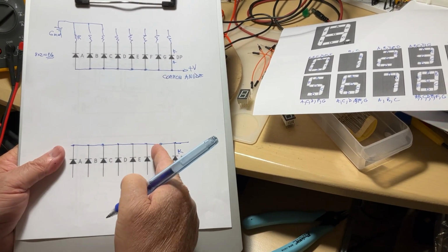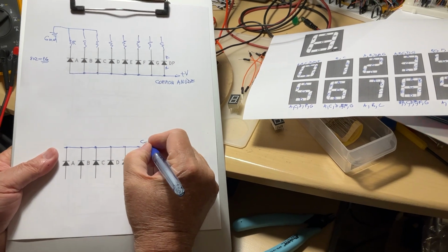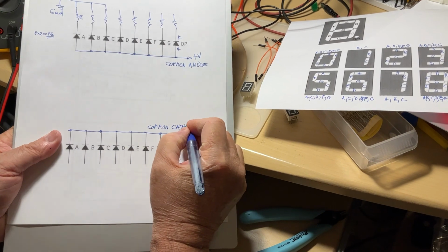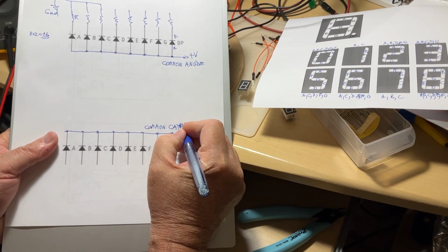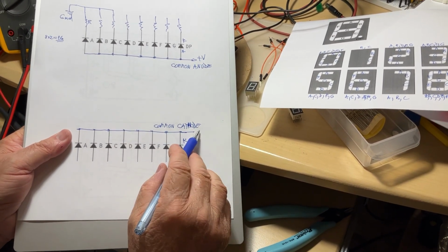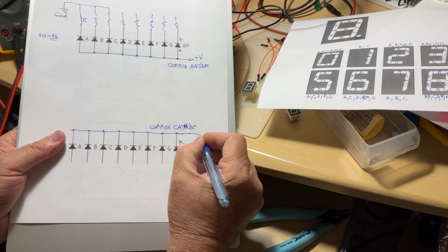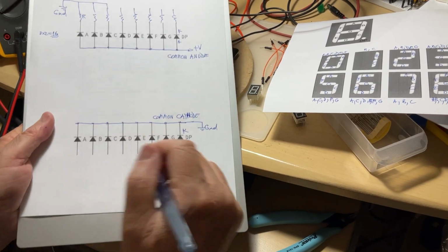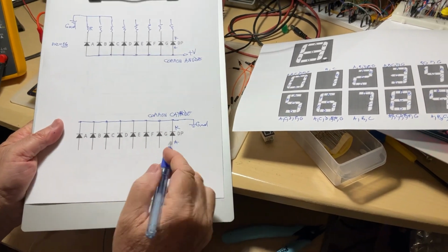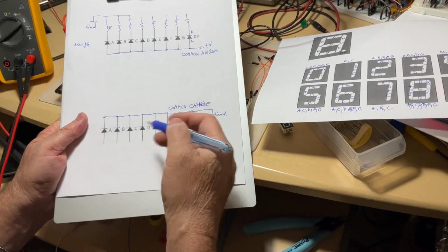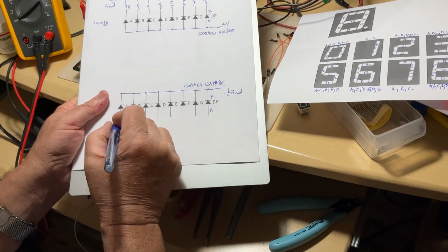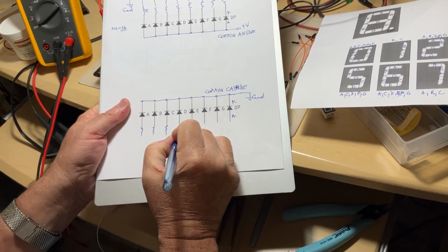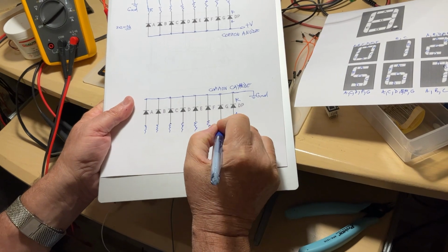So if this is the case, that kind of digit is going to be called common cathode. Why? Because all the cathodes were related together. So in this way, the cathodes are all going to go to the ground. Then, in order to make the loop and to have the power supply involved right here, you have to connect the resistors on the other side, the limiting resistors.